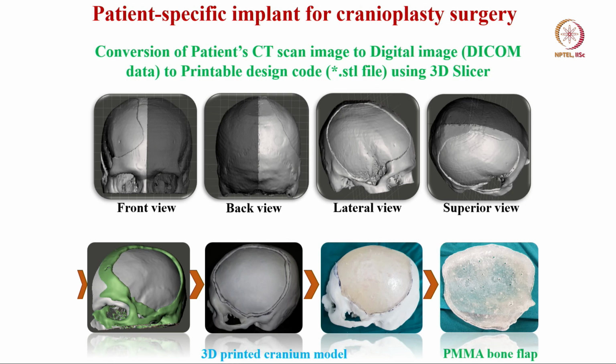So, what are the approaches that we followed in our clinical study? This is just for a single patient, showing the steps that we have taken. We have taken the front view, back view, lateral view, and superior view. These are the 4 views for every CT scan image that we considered to convert this digital DICOM data to a printable design code, that is an STL file, using 3D Slicer. So, that is the first step.